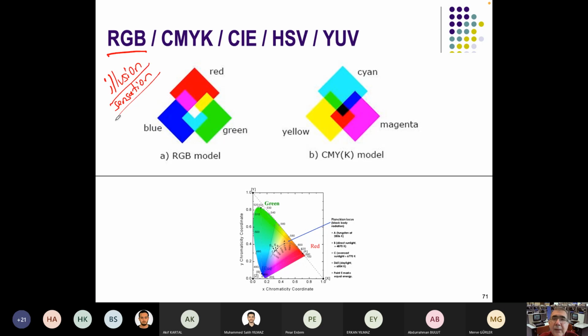Sensation of thousands of different colors comes from changing the amount of red, green, and blue. If you are generating the light, such as with an LCD monitor, TV, light bulbs, LEDs, or OLED, organic LED displays, then the RGB model should be used because you are generating light. However, if you are into printing, if you are absorbing light, that model is not easy to use.